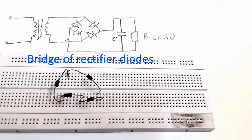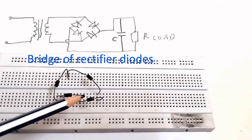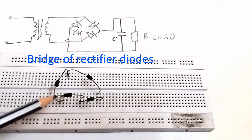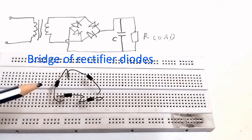Now I have roughly made the bridge configuration. This diode will correspond to this one, this diode will correspond to this one, and this diode will correspond to this one, and the fourth one will correspond to this. You can see that these 2 points are on the same line, so they will be connected with the metal strip on the reverse. Similarly, these 2 will also be connected with the metal strip, and these 2 will be connected, as well as these 2. So there are 4 connection points in the bridge which we will have to connect to other elements in the circuit.